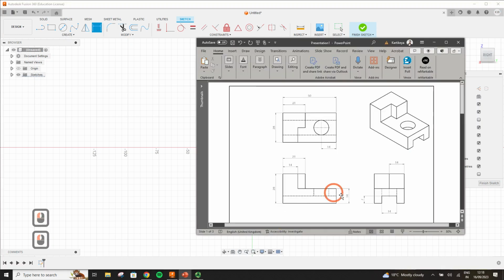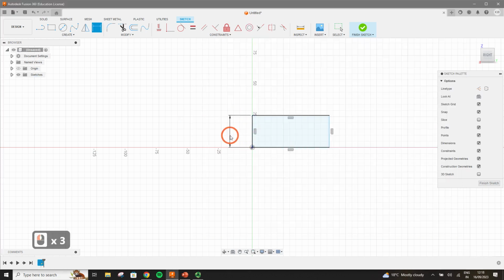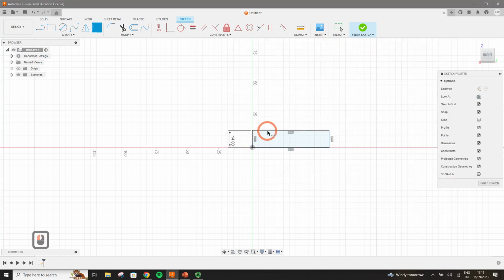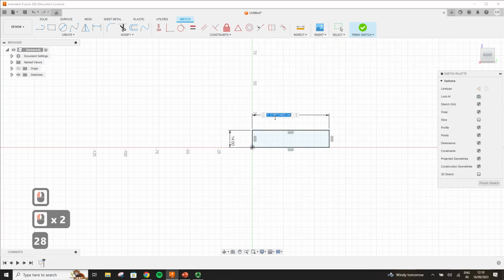So you can check in the drawing that this width is 14. So we can come back here, assign this to be 14, go back, check the dimension for the top, and you can see that that dimension is not clearly provided here, but you can assume, not even assume, you can find out how much it is. So if half of it is 14, double of it would be 28. But just to be sure, you can check that in the top view, it's actually mentioned as well that it is 28. So let's give this as 28.